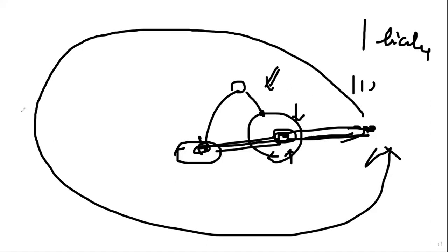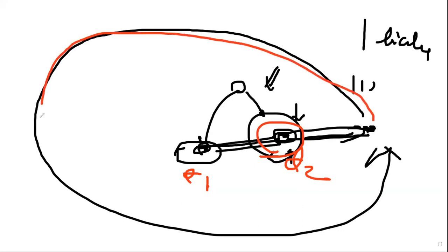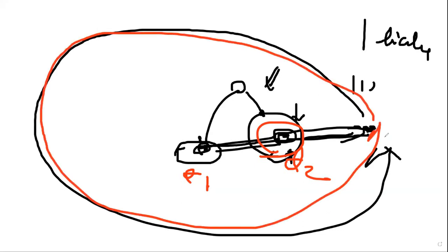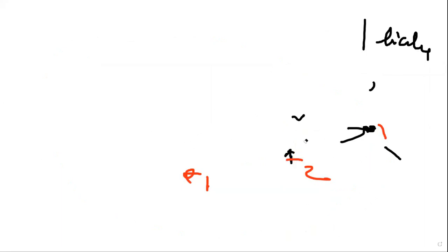So we say that singularity happens if you fix the joint here. This is theta 2 never changing. Here, theta 1 and theta 2. If your theta 2 never changes, then we talk about it as a singularity. It's only one dimensional. It drops your workspace to one dimension, and when it drops to one dimension, some locations you may not be able to reach. We call it singularity.